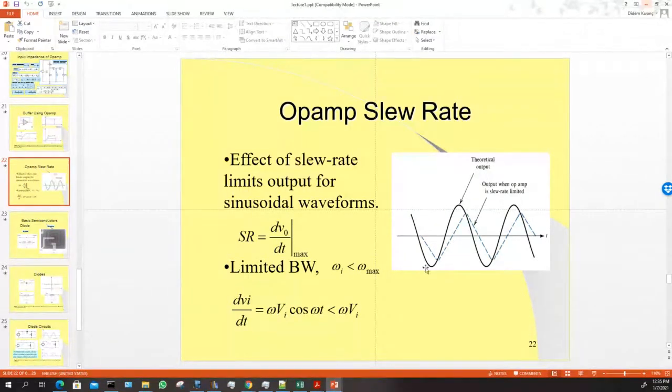So instead of seeing the black line at the output, what you see is these blue lines. This is slew rate limited. This is called slew rate. The idea here is that this is a frequency: I can't adapt to whatever frequency this black thing is. It's too far above my adaptation frequency. This is not exactly low-pass filtering, although it has a component of it, because there are sudden changes in the output signal that mean high-frequency components.